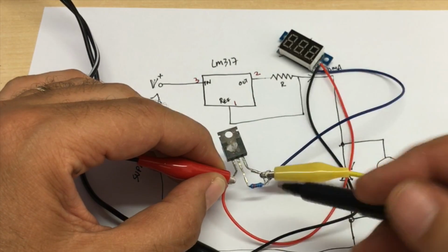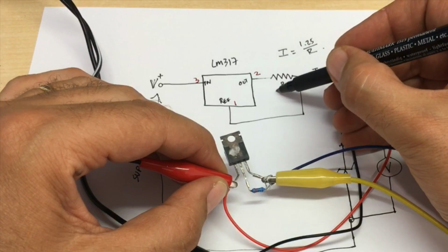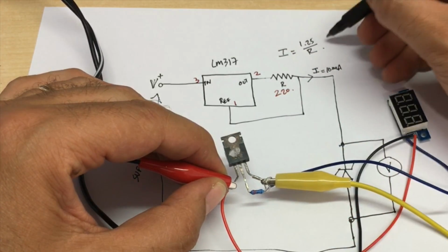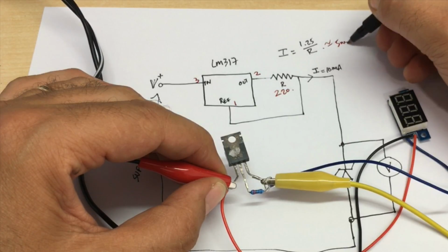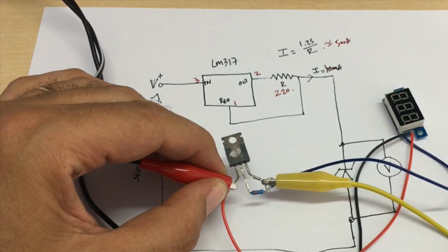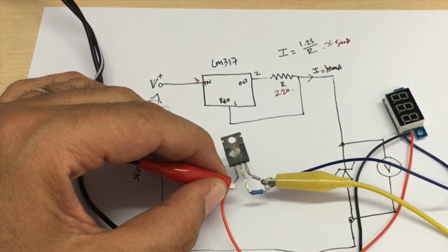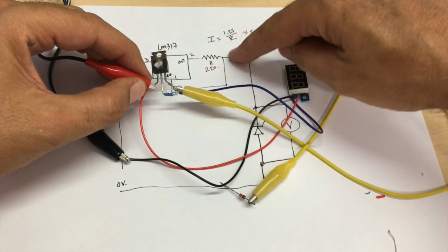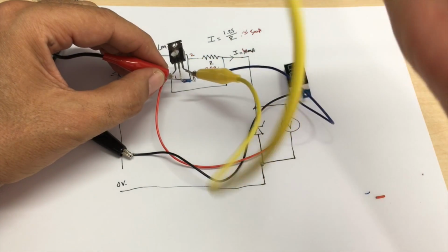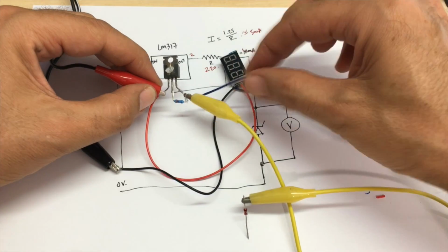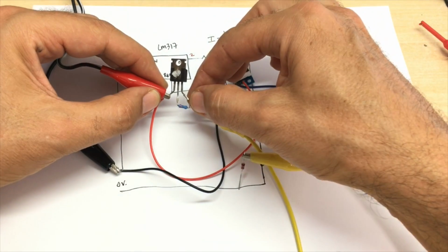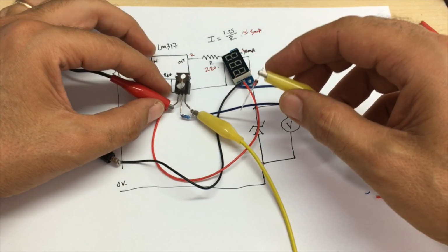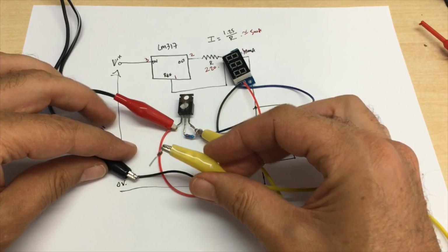We have a resistor on here, and at the moment I've got a 220 ohm resistor, which if we work this out, works out approximately not 10 milliamps, but about 5 milliamps. I just happened to put that in because I'd used this in a previous circuit. Now, what we have then is the out, that pin out there is this yellow wire. The measure tag, the blue one, goes to the out there as well, so it's going to measure the voltage effectively across the Zener, and then the Zener is going to get connected to ground.